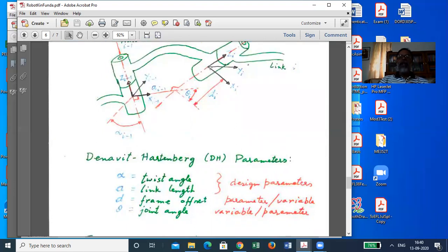By that, if you move it along this, then after this fourth unit of motion, fourth change, this frame has become completely coincident with this frame. And that means if you compose these four component motions together, one after the other, post multiplication, because each change we have made is in the local frame, then you would be representing this fellow's position and orientation in this plane of reference.